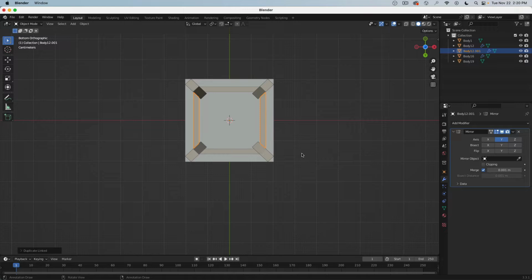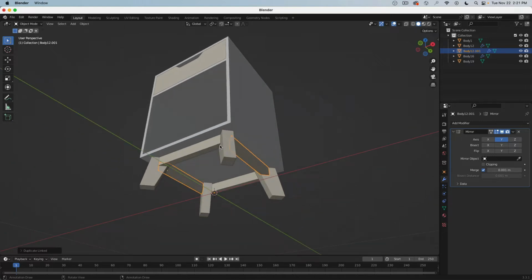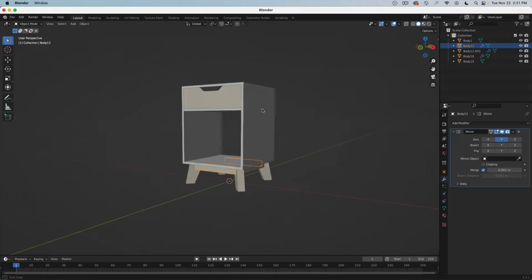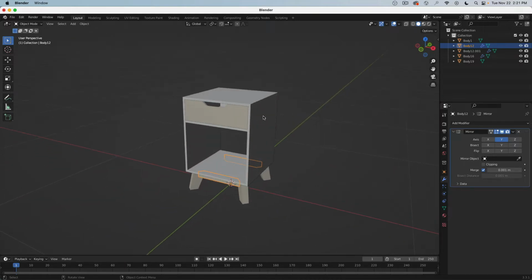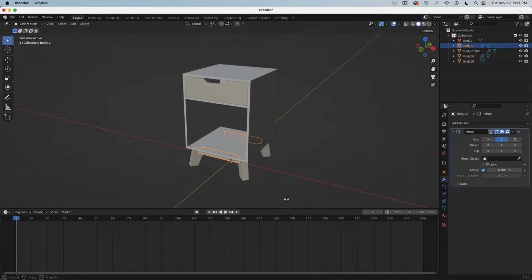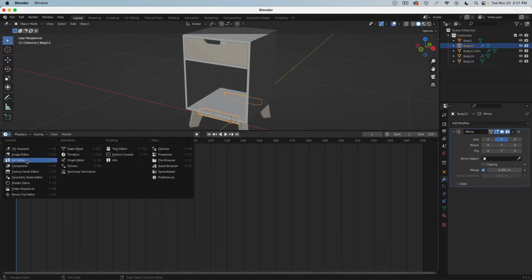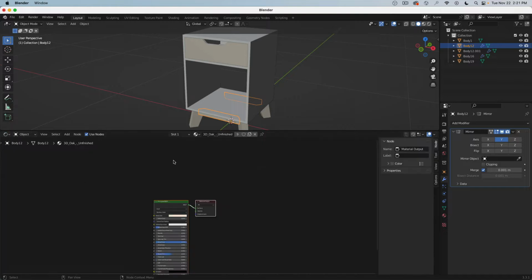So we made a clone, which then after you pressed Alt D or Option D, you instantly move. We override it by pressing R, 90 for the degrees, enter, done. So this means now if I modify this or if I modify this, they are all actually linked. So this I only have to do one time and this one time. Very good.